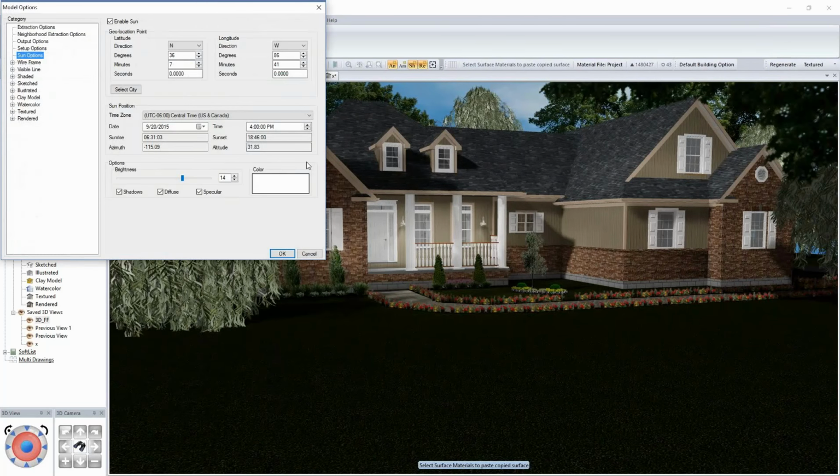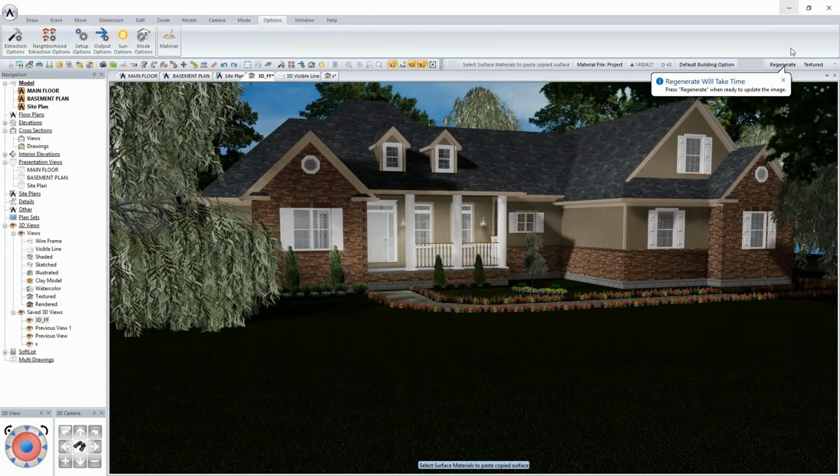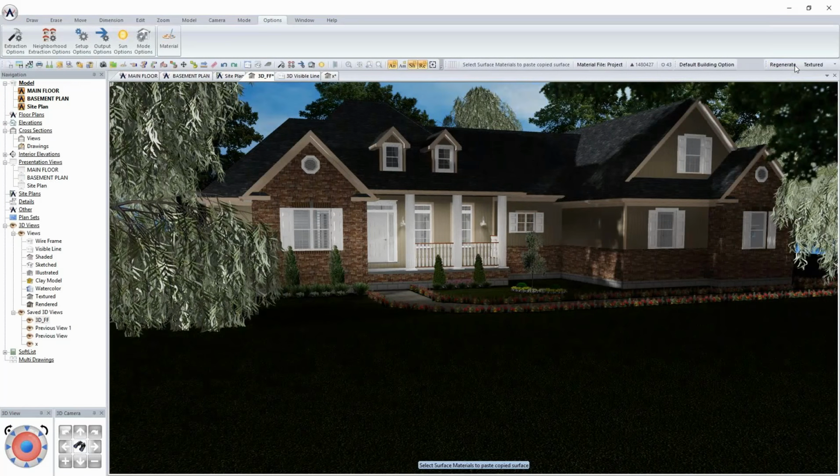You can also play with this, where if I increase this to 6, you can see at 7 p.m. in September here in Nashville, the sky has gone below the horizon. So I'm going to change that to 6, which at this stage gets much, much darker because we're moving towards dusk. This is where you can certainly see the shadows begin to pop, okay?